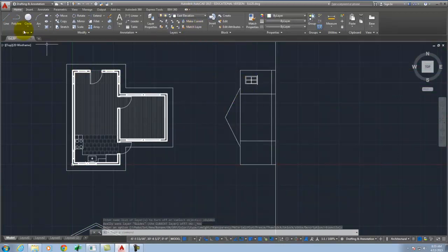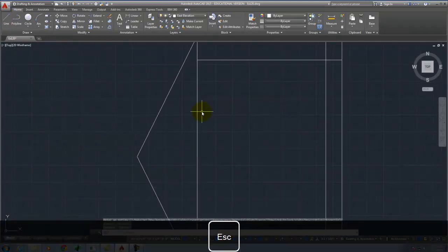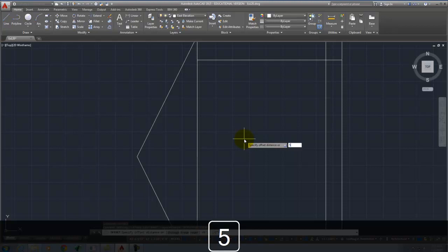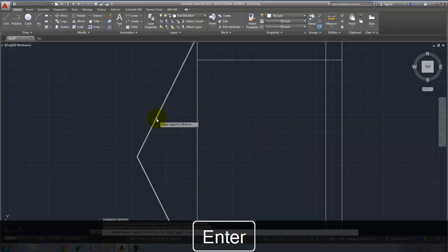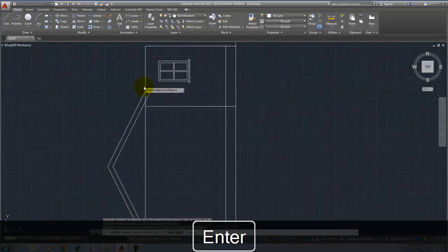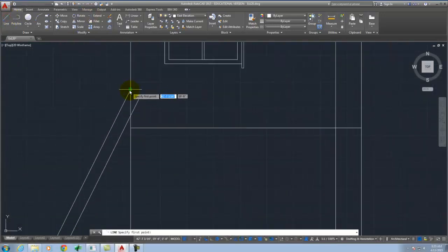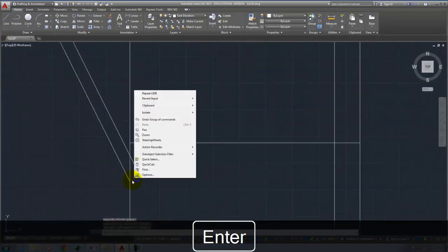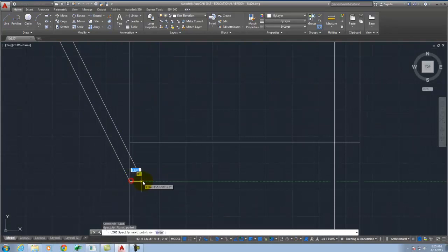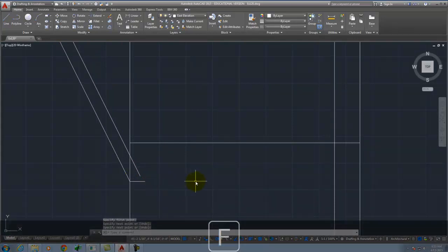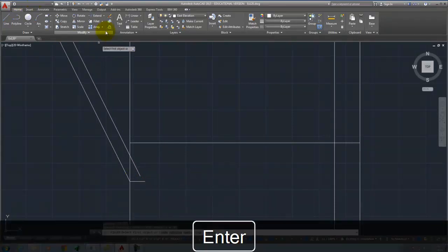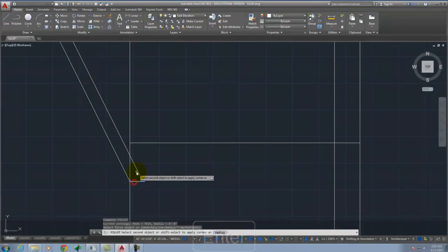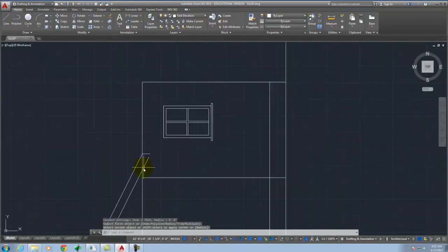And now I need to do that same stuff that I was doing before. So let me do an offset. Oops. And we'll do a 5.5. There it is. Now we need to do those straight little lines. Do there. And then I'll do a fillet right there, of those two, make them come together nicely.